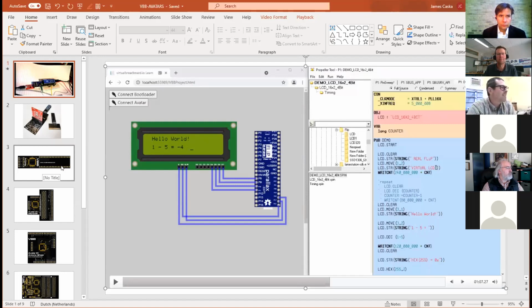I see. Where I'm attracted to the PIC is because, if you look back to 2014, I did the first version of this, and back then the PICs weren't pin mappable. So I had this problem of how I would map to different pins if someone wired it to different places. That's why I was very attracted to the Propeller in the first case, because you can map pins to any place you like when you create the decoder.